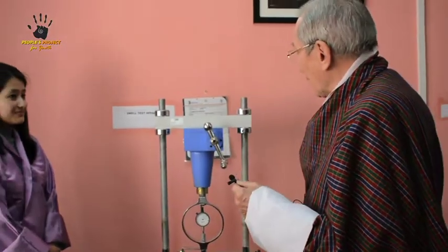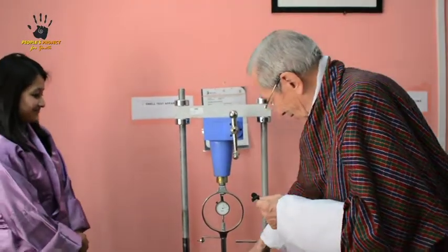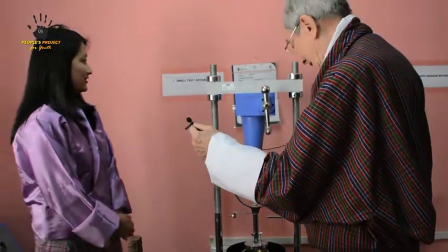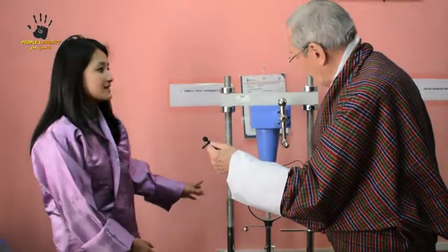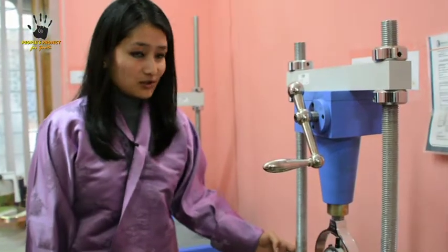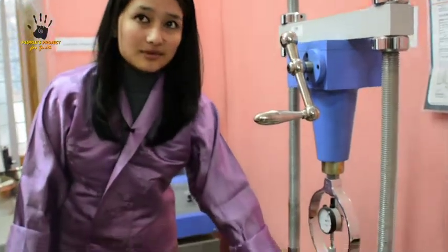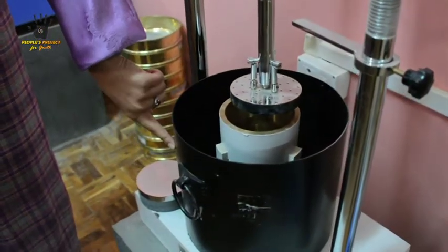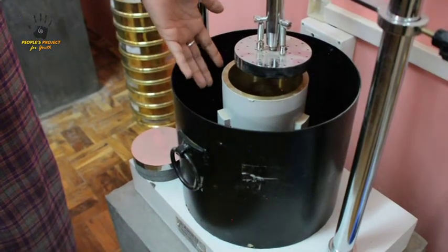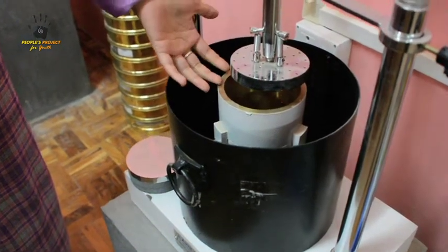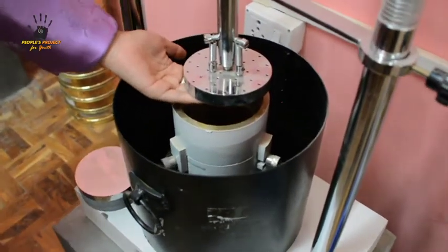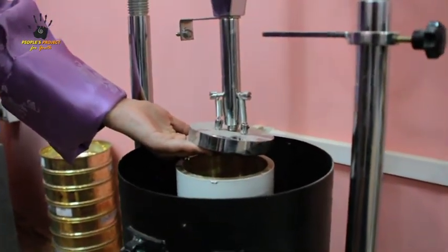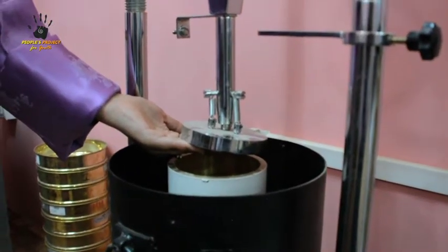We've got another machine here, a bit of a handle and a sort of a cylinder thing and a dial. So what does this do? This machine is called the soil test apparatus. So here we insert the soil sample in this cabinet, and also we pour some amount of water in the outer cabinet. And as the soil absorbs the water, the soil tends to swell, and as it swells, there is a force that's exerted, and this gauge reads the swelling property of the soil.